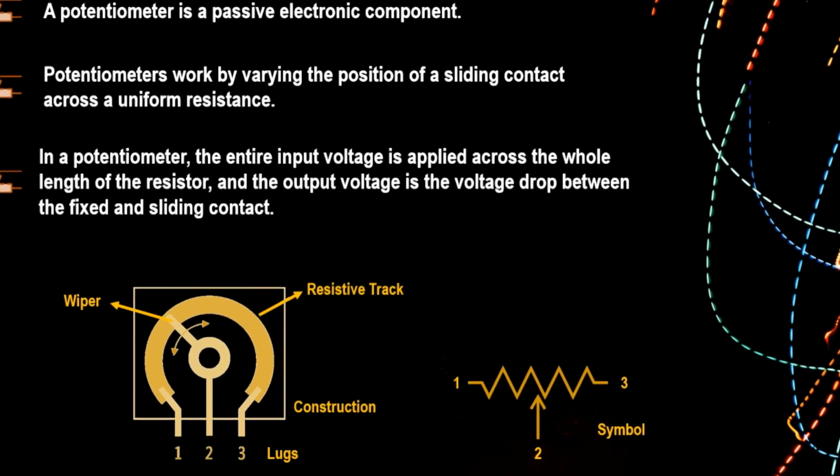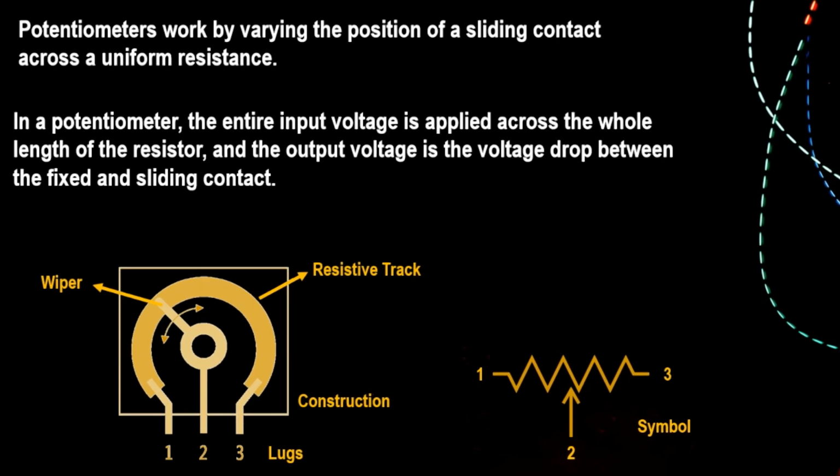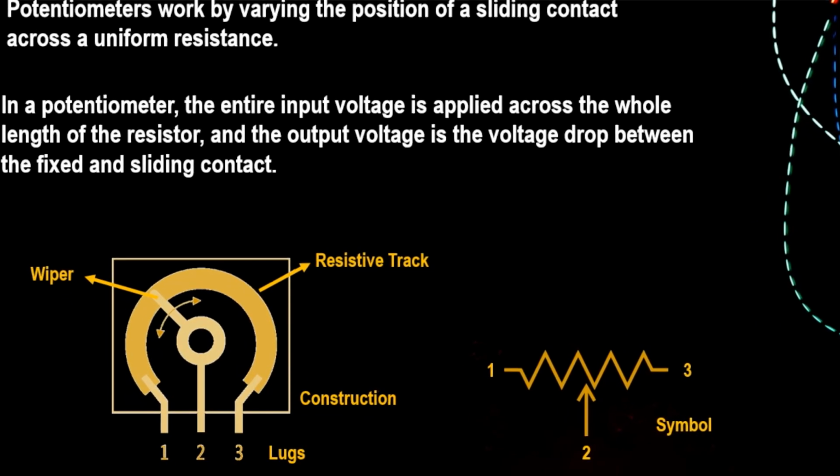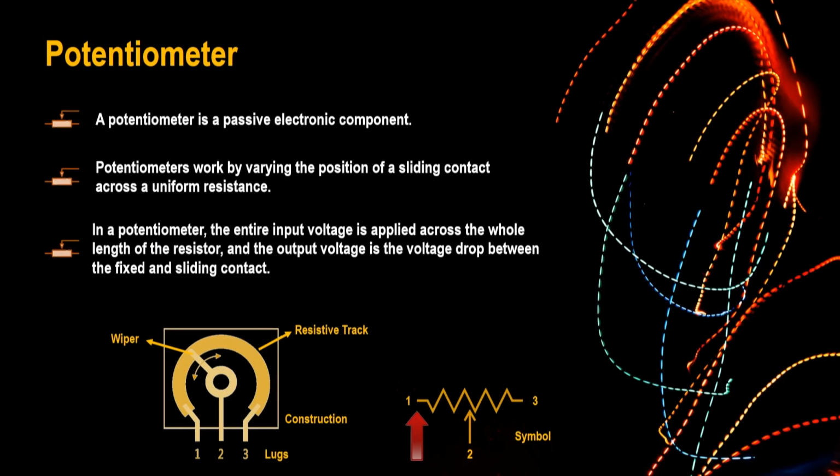So, it basically defines this portion and this portion of your potentiometer, and then in the middle we have one variable pot that we can use to adjust the resistance level of this potentiometer. So, while dragging it from one position to another position and taking it back, it will help you to get different values of resistance for your circuit ranging from 0 to the maximum value of your potentiometer.